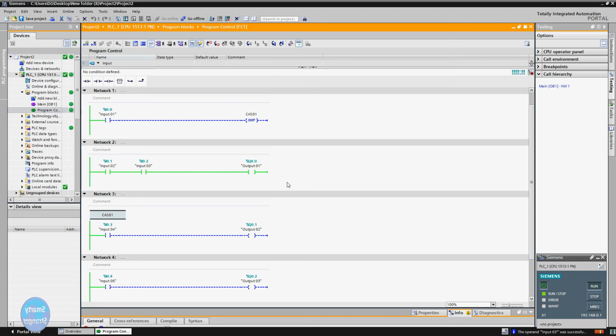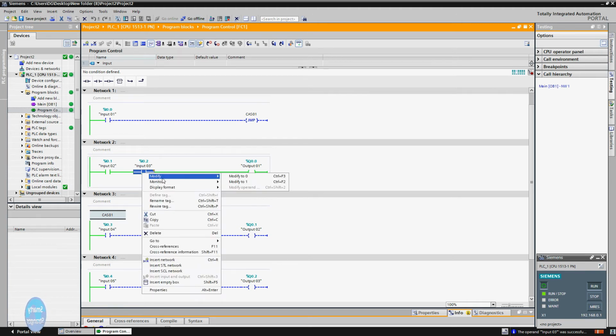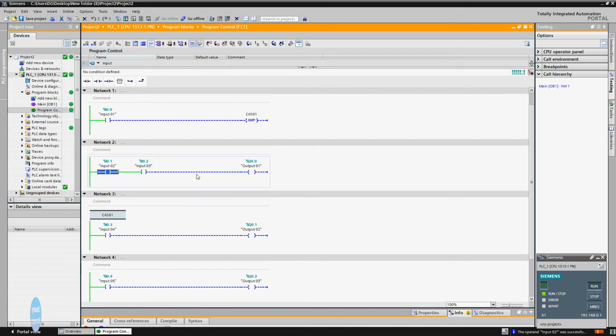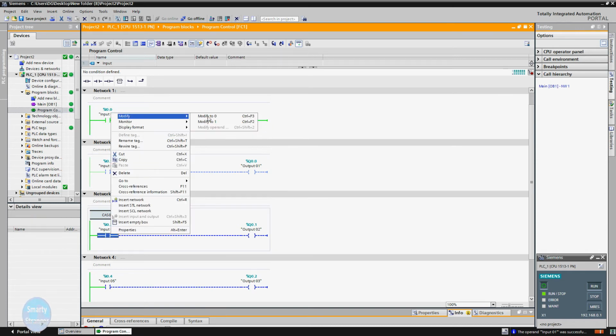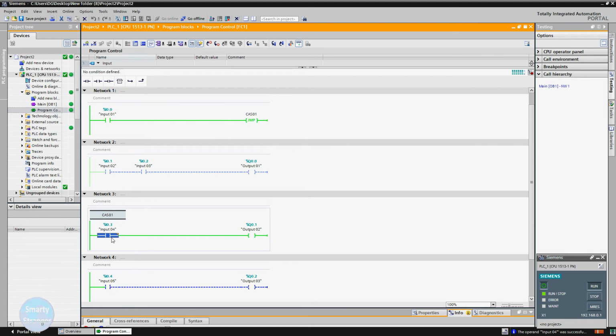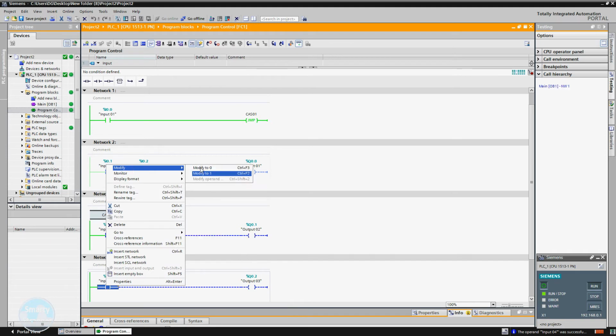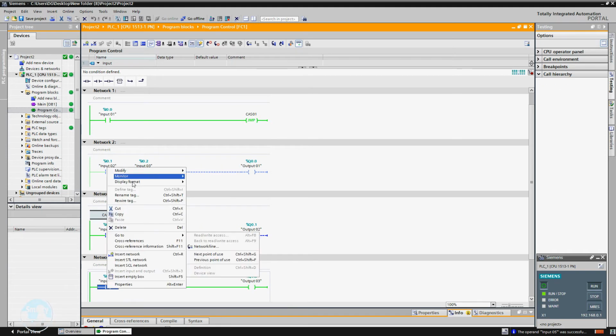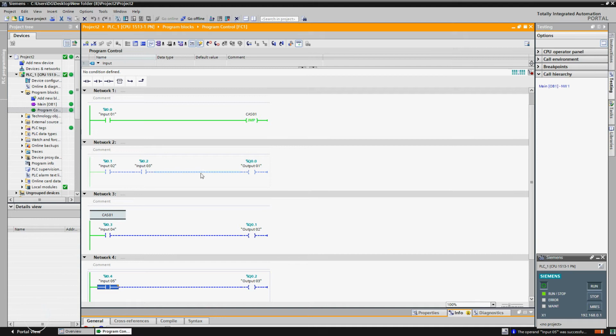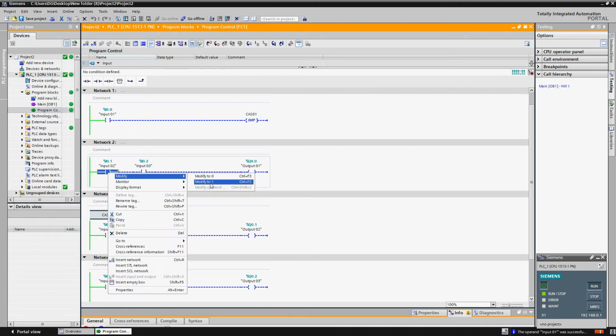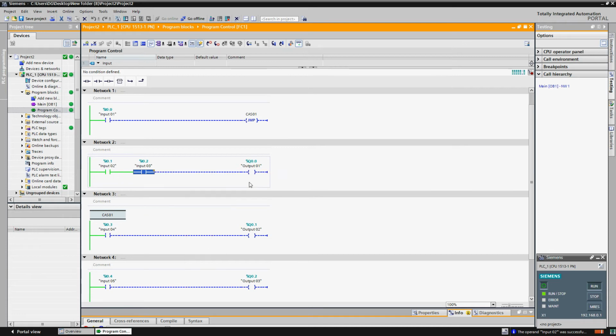When we activate the jump instruction in network 01, it will bypass network 02 and move the program execution to network 03. Network 04 is also operative in this condition. When we de-energize the jump instruction, network 02 will be in operative condition, and execution is possible.